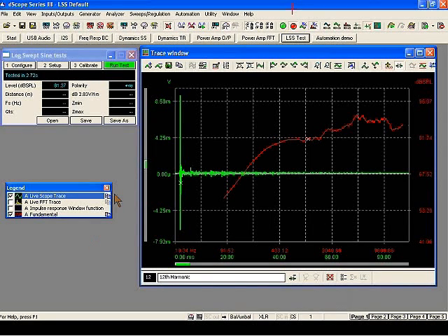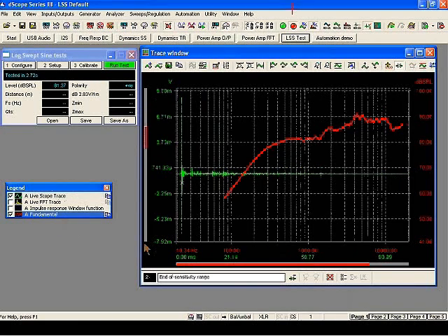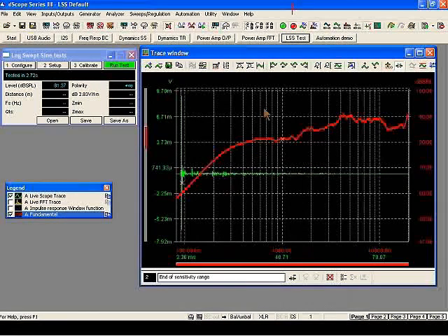But what we do is we set up a broadband stimulus in the signal generator, and we compare the FFT of that data to that of the data that arrives at the analyzer. Once we have made that comparison, we can mathematically derive this impulse response, and as you'll almost certainly know from the feedback you've given me so far, the advantage of using an impulse response technique for an electroacoustic measurement is that if we don't have a perfectly anechoic measurement environment, we can isolate the fundamental impulse from any discrete reflections.